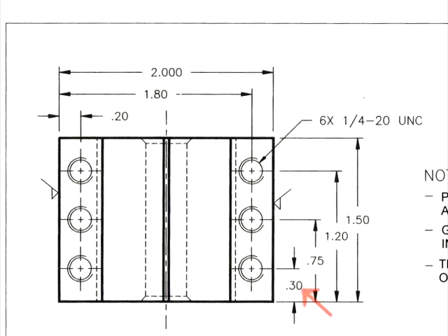And whenever possible, your dimension lines should be cut and the dimensions affixed somewhere close to the midpoint of the line. But as we can see here, sometimes there just isn't enough room for symmetry. So if it has to be off center, well, that's okay. When we use a dimension line that only goes to one side, well, it's not called a dimension line, it's called a leader line. And again, they attach a dimension to an entity.